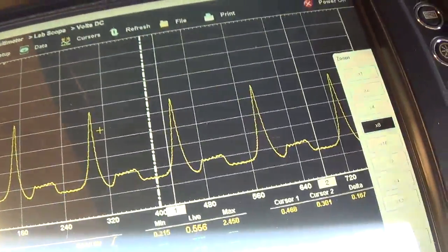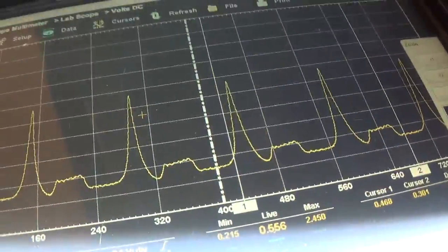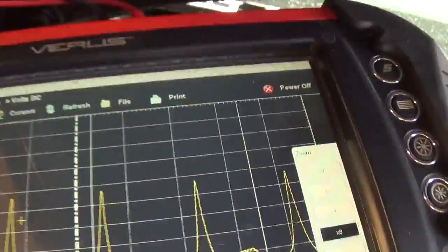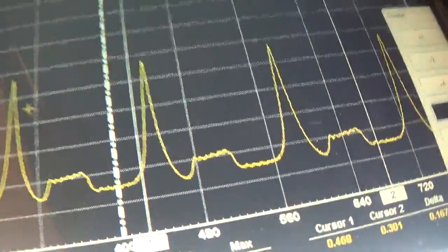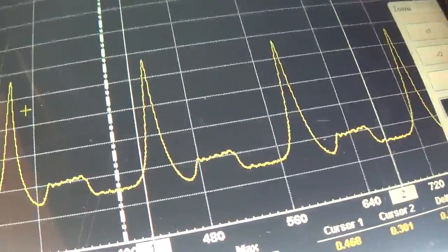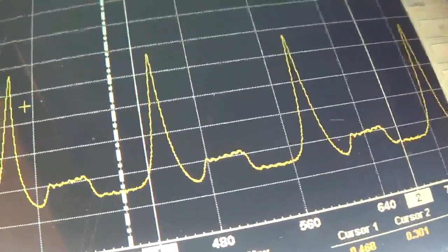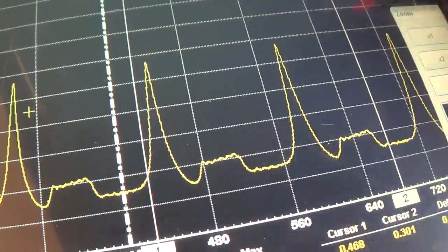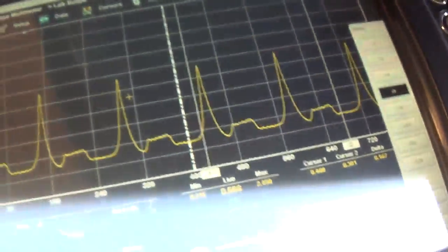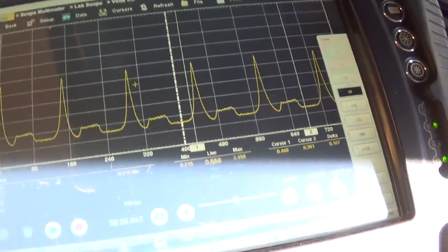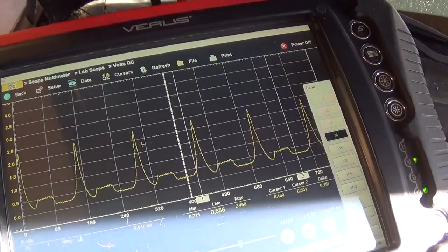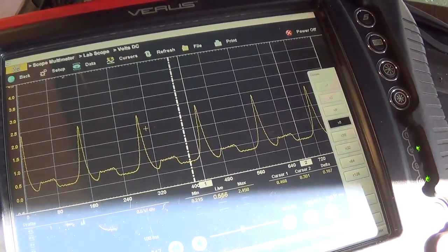So in this case, the relative compression test was much more evident in terms of compression loss. And then the leak down test showed us which valves are leaking. In this case, the pressure transducer is not going to tell you which valves are leaking, especially if they're leaking slightly. It could be leaking out of anywhere. The only thing we can say is that cylinder is leaking, okay, on the compression stroke. So there's that. I think enough playing around with the scope. Let's get this head torn off of here and actually examine it, do a visual inspection on those exhaust valves.